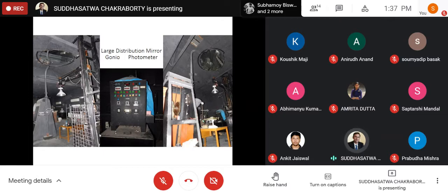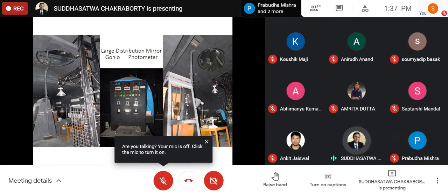So if somebody asks you why we need to have a mirror, it is just to ensure that. But the baffle is required because if mistakenly any direct light reaches my sensor, it will not be capable of differentiating whether it is direct light or indirect light. So if it is direct light, my point source realization will be completely invalid. My measurement will be completely erroneous.